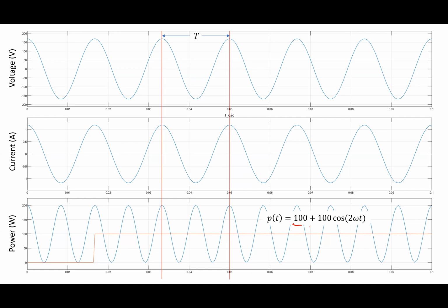But if I have a 3-phase system, each of the phases has pulsations that, when I add them together, go away. So a 3-phase load at 100 watts draws 100 watts. Its average and its power as a function of time is the same. That turns out to be, if I'm building a motor or something like that, really nice on the motor. Motors don't like this pulsation.